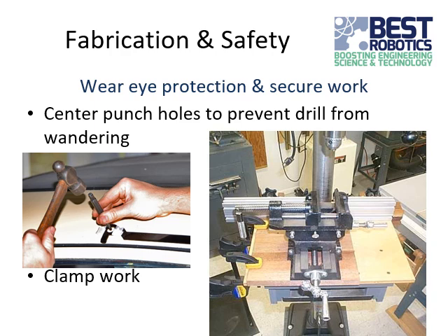You don't want to sit there and hammer it with multiple hits, because it can bounce around and make multiple holes, which kind of defeats the purpose, because then the drill can go from one hole to another, and the whole point of this is to keep the drill from moving. And then clamping your work is always a good idea.